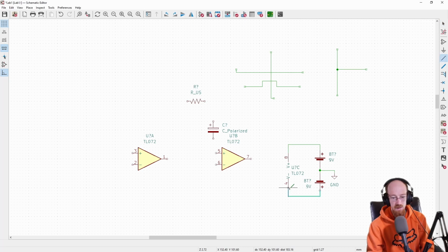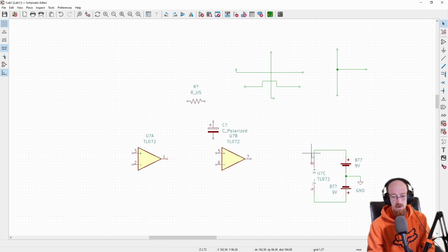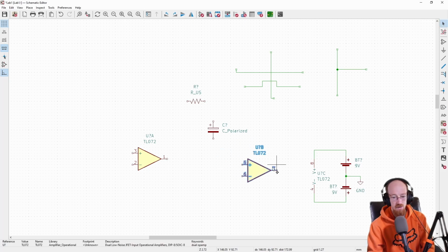And like this. So this is the same thing as our battery being connected to the positive chip. And this is pin 8, the positive voltage source for pin 8. And then pin 4, we get the negative voltage source. So you're going to see this in the corner of some schematics that you'll be making. And this is exactly what it is. But we can see here ground, the batteries, how to connect things up, like pretty nice. And so this would mean that, on the chip, pins 5, 6, and 7 are connected some way, pins 1, 2, 3. So as you get to those, we'll talk more in depth about what these mean. But in KiCad, that's how you add them.